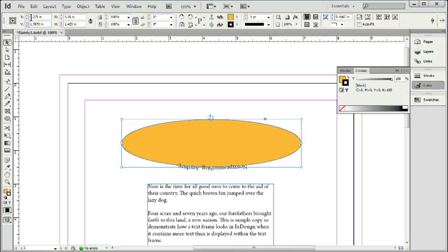Now go to the top edit box, 4 columns from the left. This is the Rotate Selection edit box. Double-click to highlight the default 0-degree setting in this box, then type 180 and hit the Tab key to enter your value and rotate the oval on its own axis, placing the type on top. This is the easiest way to turn that text right side up, but there are other ways too.